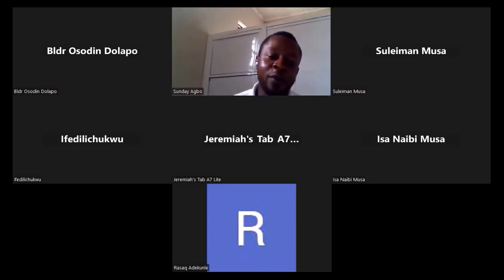So now, at that point, if you are working within Nigeria, like here in Kaduna, as I make reference, we use UTM Minna 32. Possibly in Lagos, because I clearly know that I did the work recently in Lagos, they are using Minna 31, okay? So you can search more about it online and know your locations and then know which particular projected coordinate system actually works for you.